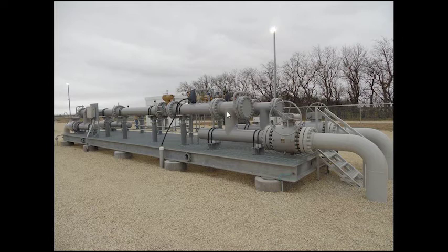It's a very popular thing, but in the process of doing this, I feel like there have been some mistakes made along the way. And one of those is this close coupling of these T's. That is not a preferred method for doing these installations. You end up with some flow distortions that have to be accounted for.